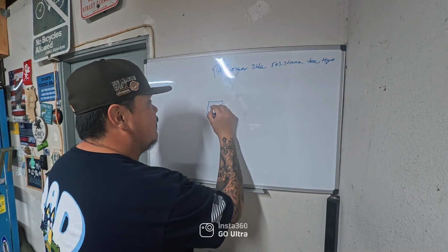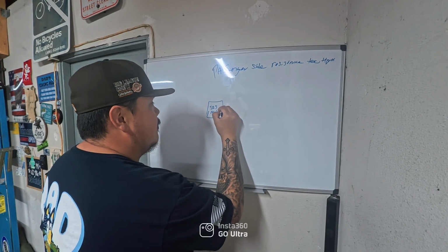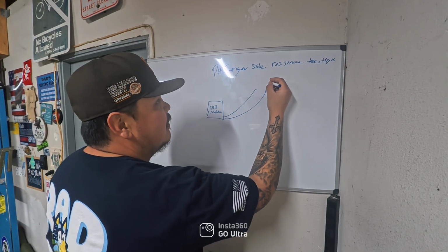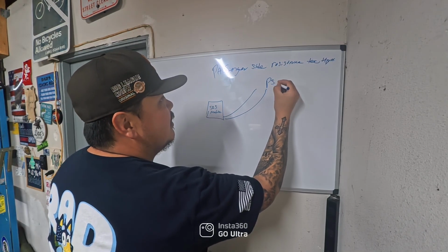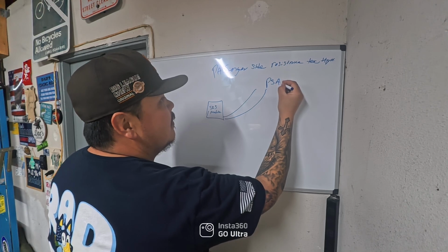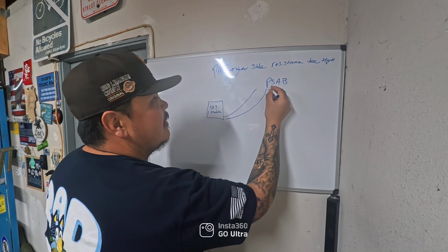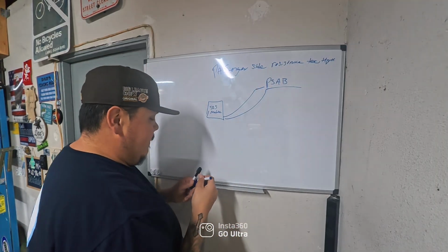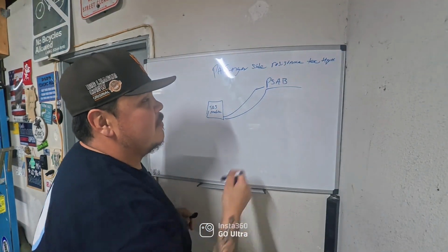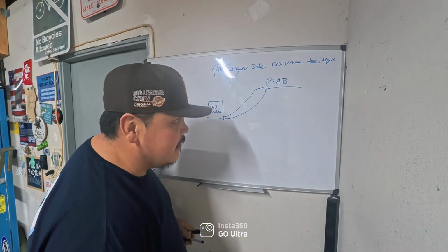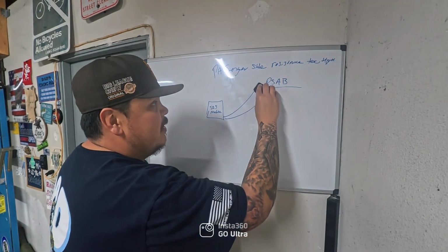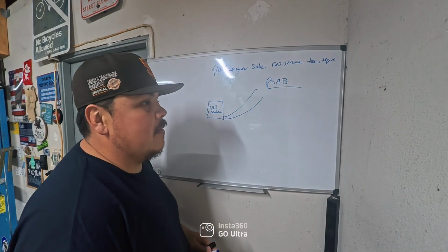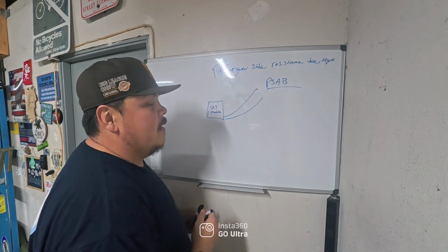So we have our SRS module, and all of these airbag components are 2-wire circuits. So passenger side airbag, PSAB, we have 2 wires going to it. If you have a resistance too high trouble code, what you need to do is access the component that has the trouble code, and then you got to install a dummy load.